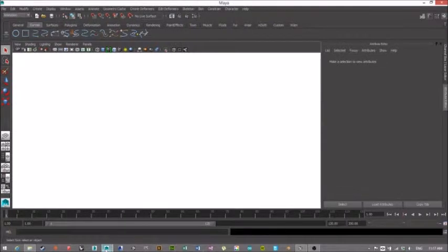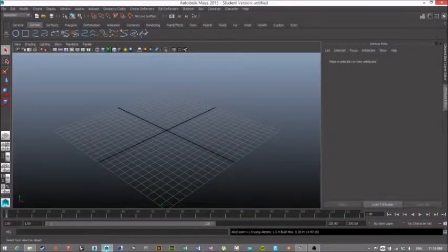Yep. It's a mesh. Yeah, it's a mesh. Can SketchUp export an OBJ? If it can export an OBJ, then you're fine. You just export an OBJ. Whenever you're dealing with meshes, you want it to be OBJ. It'll probably be cleaner that way than if you were to bring it into Rhino, because it is a mesh and it'll understand the triangulation and stuff. But yeah, meshes are always just exported as OBJs.